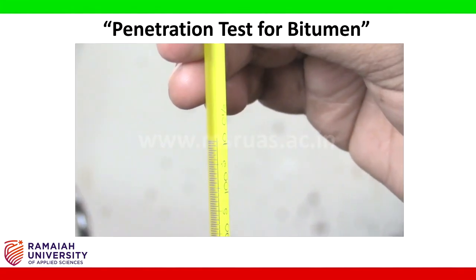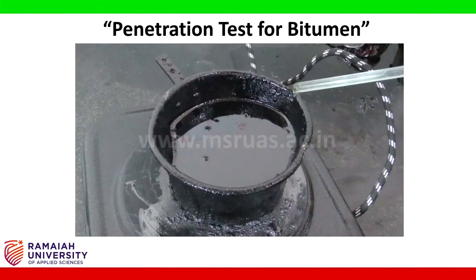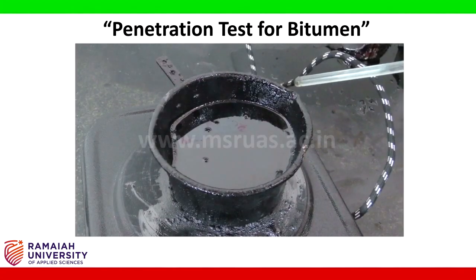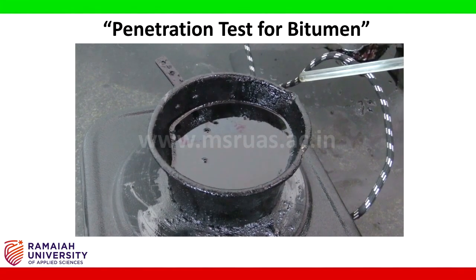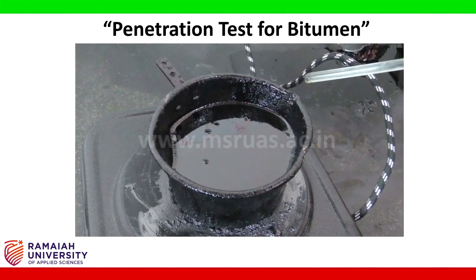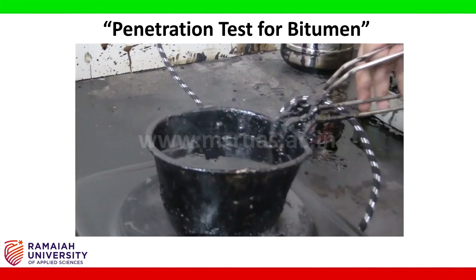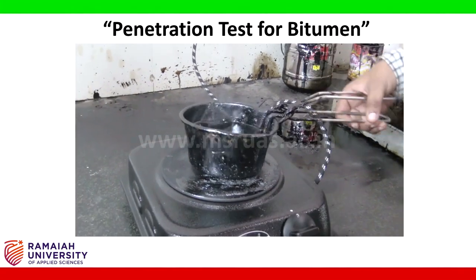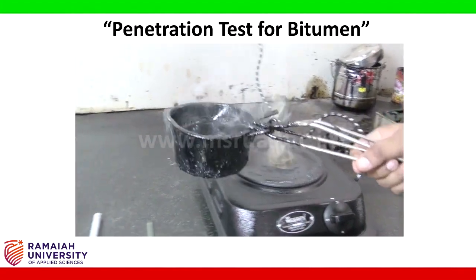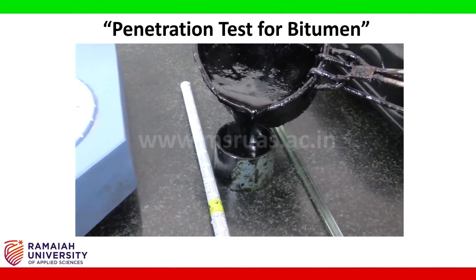Yes, now the bitumen is reaching 100 degrees centigrade, 115 degrees centigrade. What we will do is pour this bitumen into the testing mold. We just use a spatula, hold it and transfer this pouring temperature bitumen into the testing mold.